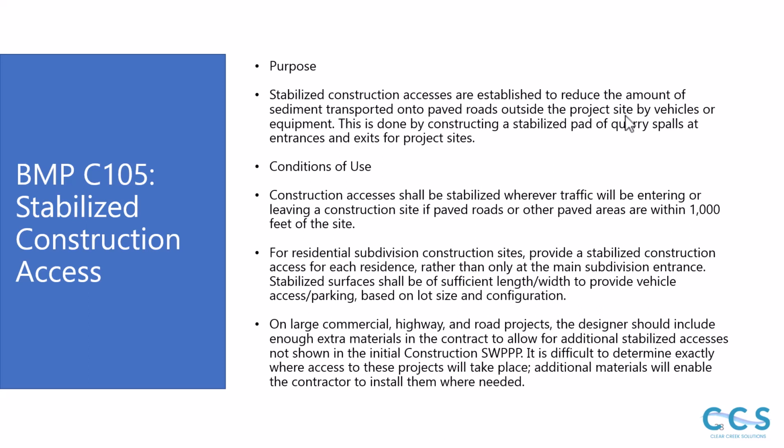For residential subdivision construction sites, provide a stabilized construction access for each residence rather than only at a main subdivision entrance. Stabilized surfaces shall be of sufficient length and width to provide vehicle access and parking based on lot size and configuration.